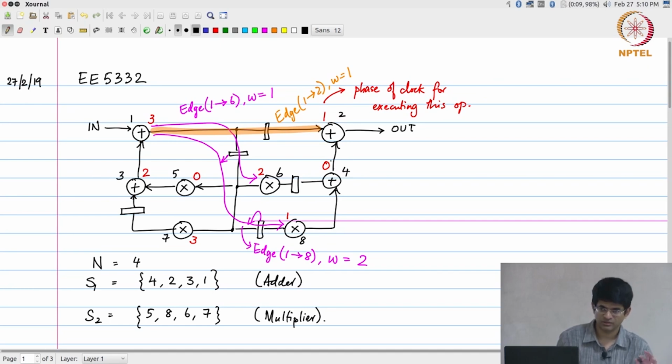Yes, but what I am saying is, you remember what I said, this is just a data flow graph. When I say that it is getting its inputs from multipliers, what I mean is the functional unit. From 8 to 4. Oh yes, I am sorry, thank you for pointing that out. That's because I missed a register over here. So yes, that is an important point. There is a register out here. Without that, the df would have been negative and there would definitely be a problem. Thanks for pointing that out.